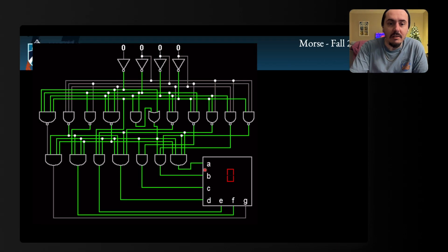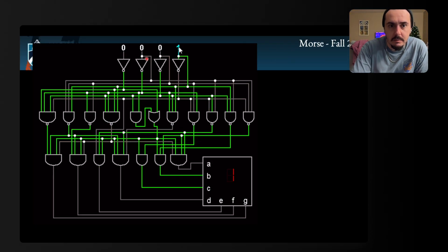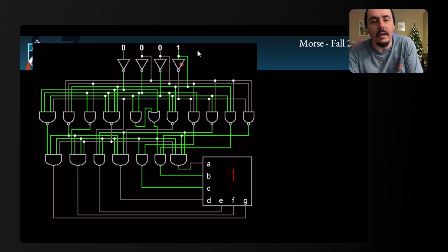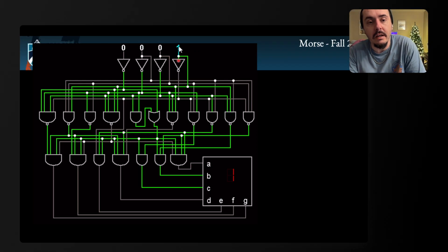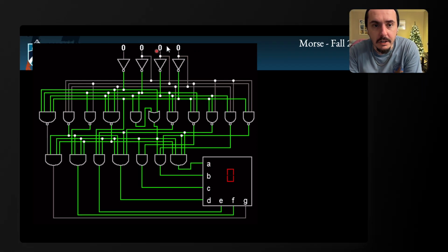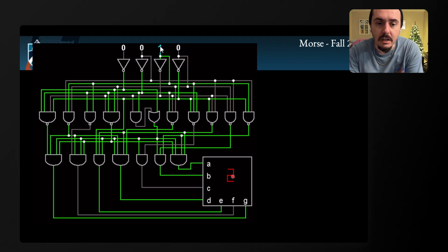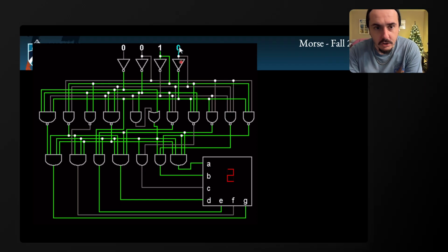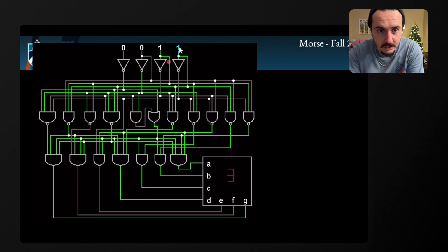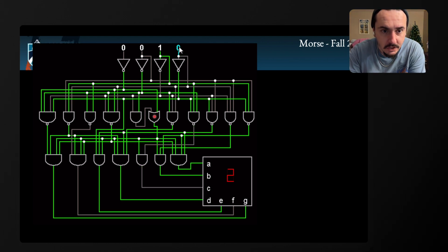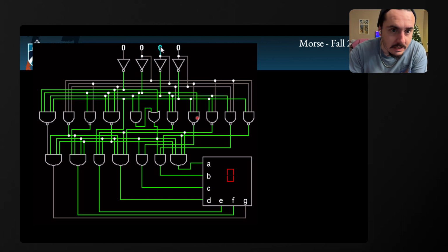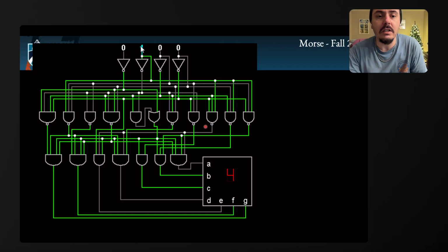And we can look at things like this and actually identify what each of these components are. This system right here is built so that you can put in a binary input here, and it gives me the actual decimal quantity here. These are all NOT gates. Here's an OR gate in here. The rest of these look like they're pretty much AND gates or NAND gates. All of these things we've looked at.